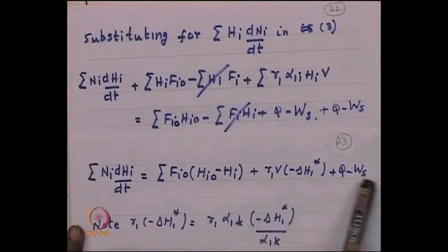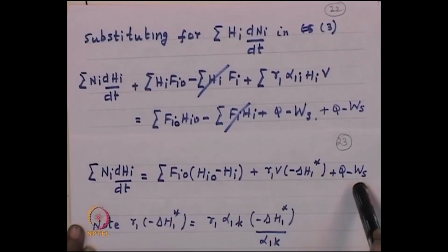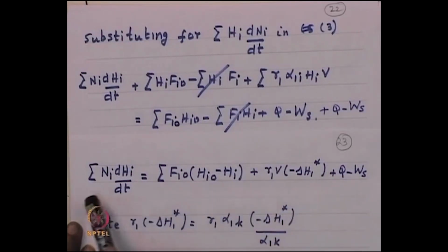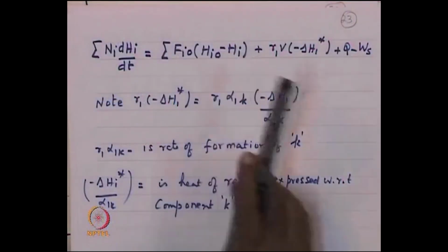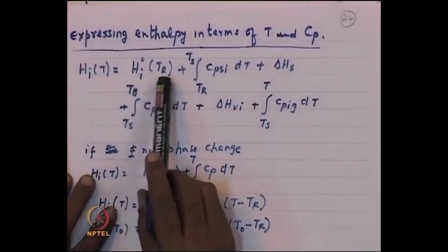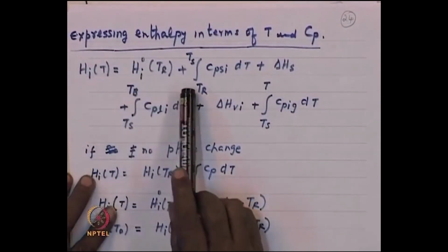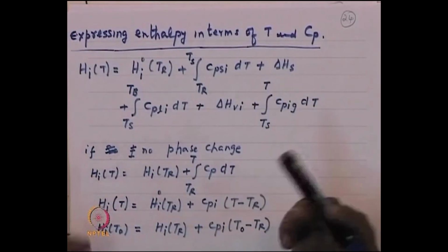So, in this form, the way in which this equation is written, it is probably the most general form in which you can write a chemical reactor energy balance. It takes into account all sorts of variations that might occur. Having said that, we recognize that this term H_i can be put in terms of temperatures, because the enthalpies are available to us in terms of a standard heat of formation plus various Cp delta T, which takes into account the effect of the specific heats.